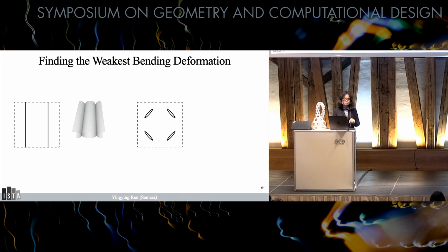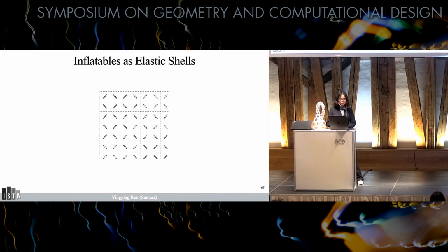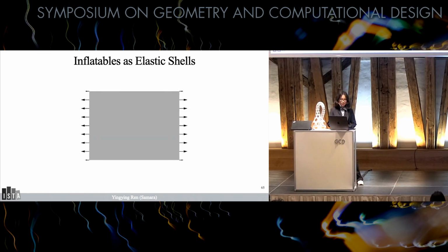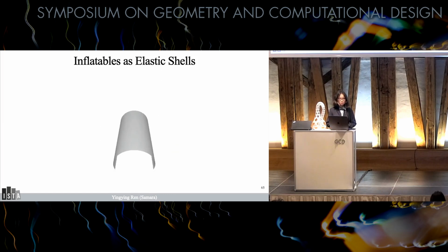For parallel tubes, the fusing lines essentially function as free hinges that exert zero resistance to bending. For more complex patterns, such as this one with the elliptic holes, it's unclear how we can directly infer the bending behaviors from the geometry, and instead we need to turn to physics-based simulation. The general idea that we'll use to analyze a fusing pattern is to consider a homogeneous material built from an infinite tessellation of this pattern, because then we can apply standard theorems from continuum mechanics to analyze the stretching and bending stiffness of this new metamaterial.